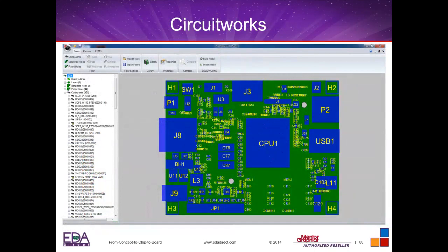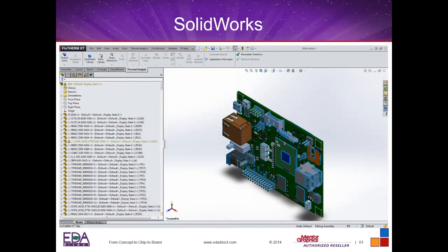It easily pushes into CircuitWorks, and by pushing into CircuitWorks, we can push it into SolidWorks very easily. Same thing for Pro E, Solid Edge, and NX as well. And should the mechanical group decide to move some of these components because maybe they're interfering with something to do with the mechanical enclosure that they have, he can also move these components in his tools, SolidWorks, Pro E, whatever, and then we can back annotate that into the design, and it will let us know exactly where those components moved, and we can agree or disagree. It's a nice way to talk back and forth with your mechanical group.